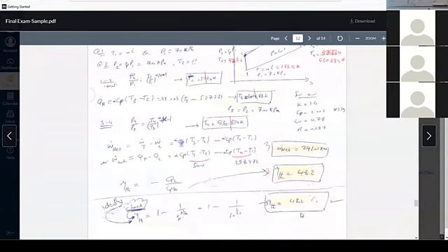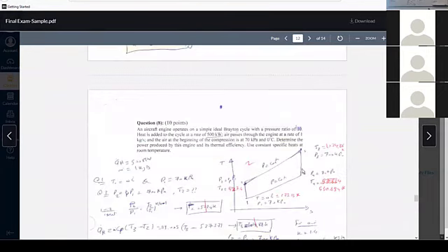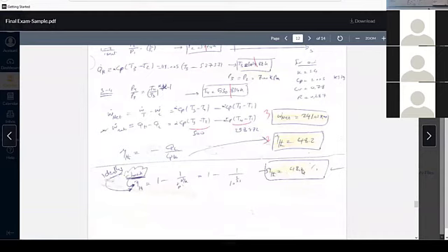Okay, guys, make sense? Thermal efficiency is 1 minus Q low over Q high. And there is a very good check for you here. You got Q high and Q low from the temperatures. That's a very, very important and good check for you. You can get the thermal efficiency, yes, but you can check it because everything is ideal. You can say 1 minus 1 over rp to the (k minus 1) over k. And you have rp, which is 10. The pressure ratio was 10. So you can directly get this number, 48.2%, which is exactly the same as this one. There is no error.